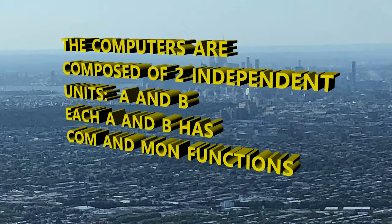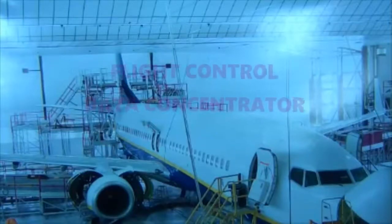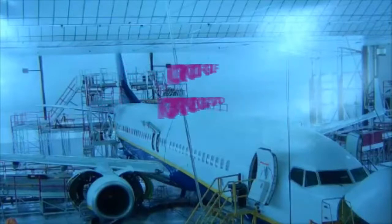But what about the other way around? It needs the feedback to see what the angles are, where they need to be, or whether there is a defect on the actual physical control surfaces. So it needs that feedback, and it gets it through the flight control modules or electronic modules, which change that analog to digital so that the computers can take that data and make the changes accordingly. Your flight control data concentrator is part of this whole commanding and monitoring of things.